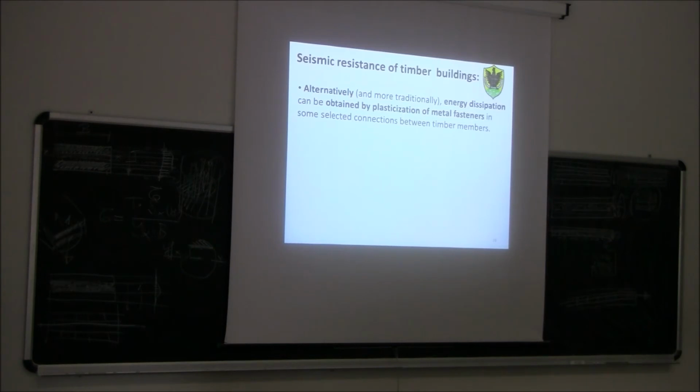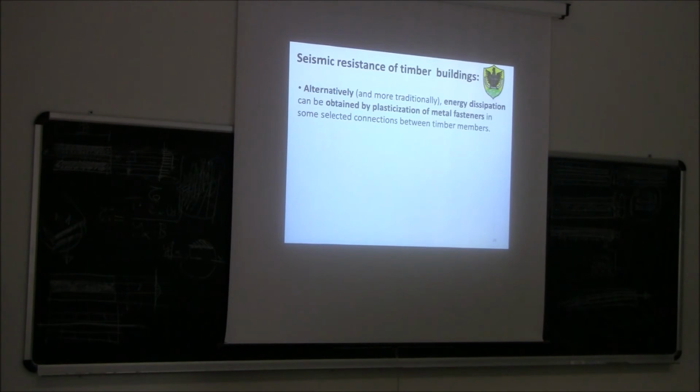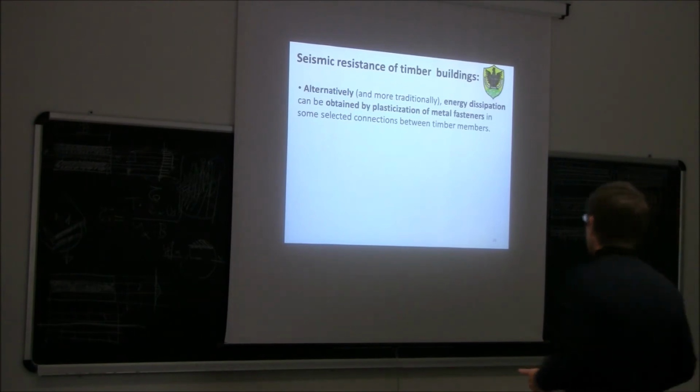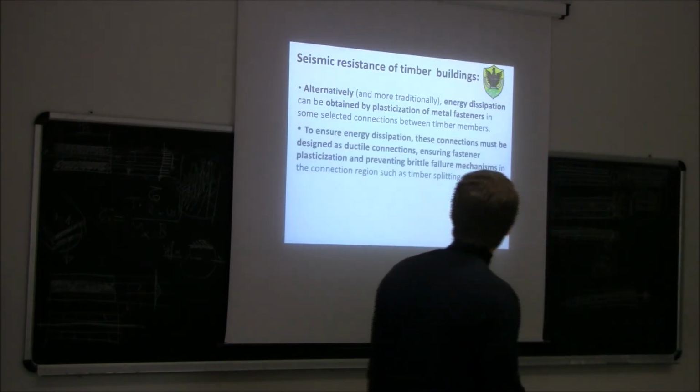So the idea is that in the joint region, I will have some metal fasteners, nails, screws, dowels, bolts, whatever you want, and I can exploit the possibility that those fasteners may plasticize during an earthquake. So they may provide the energy dissipation that I need for getting a dissipative behavior.